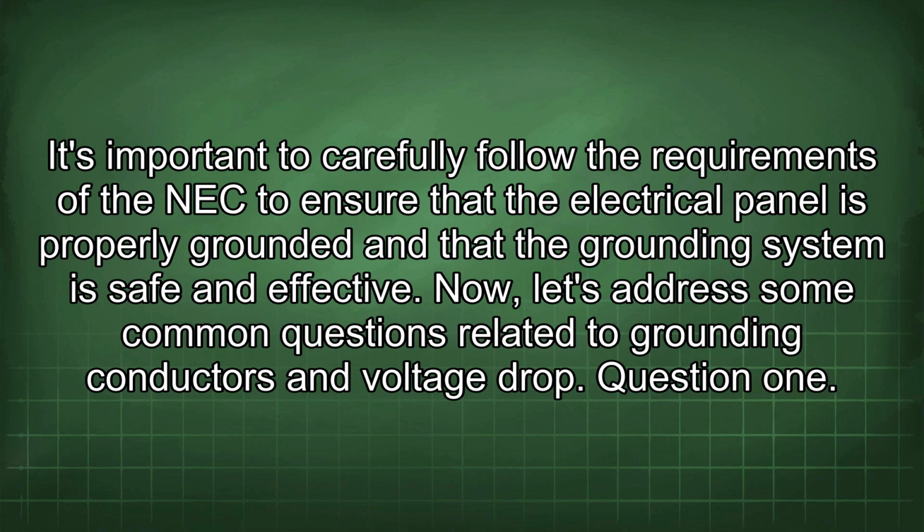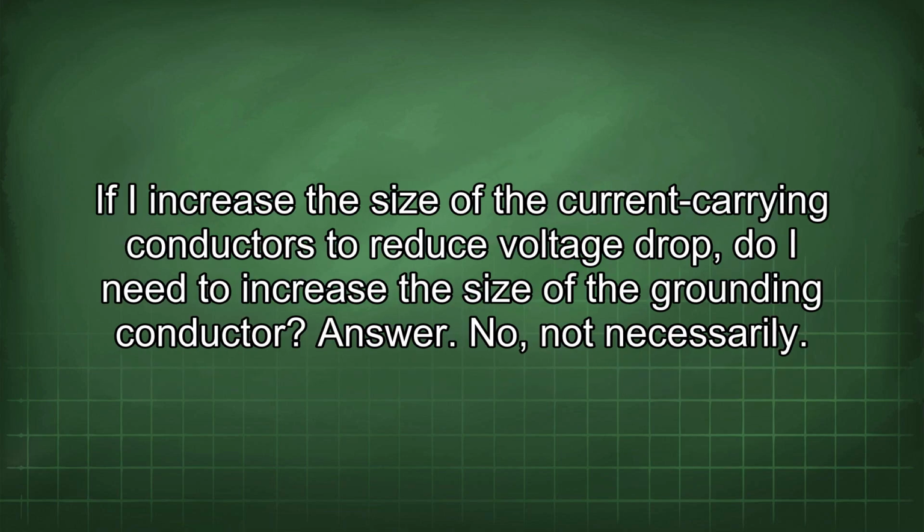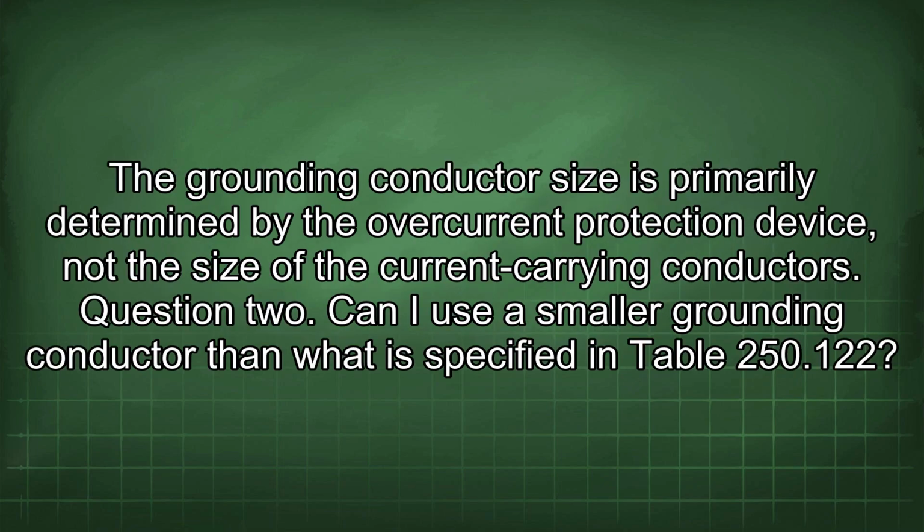Now let's address some common questions related to grounding conductors and voltage drop. Question 1. If I increase the size of the current carrying conductors to reduce voltage drop, do I need to increase the size of the grounding conductor? Answer: no, not necessarily. The grounding conductor size is primarily determined by the overcurrent protection device, not the size of the current carrying conductors.